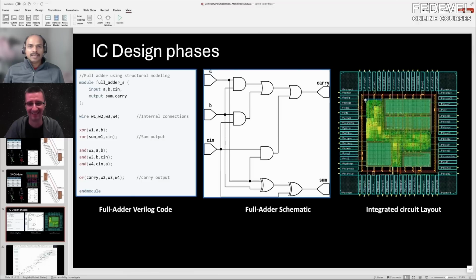I see. Talking about the placement, what we call floor planning, yes, we do see those challenges sometimes. In chip design, there are configuration settings that you could set, and it depends on the scanning width the autorouter can do when it is routing. Can I scan the next 20 tracks, 30 tracks to see if I have some wiggle room or something?